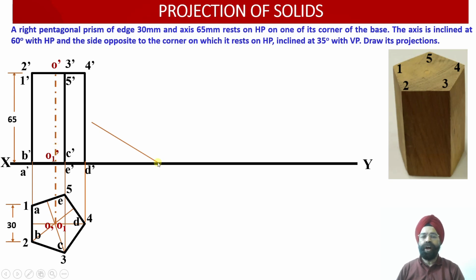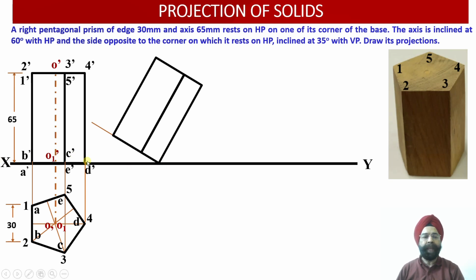So once we draw the angle of inclination of the base as 30 degree, now point D dash will be shifted over here as point D1 dash. Now this is our point D1 dash. The moment we obtain point D1 dash, now you see, using rectilinear distances principle, we are going to transfer these front view elevation projections into the new inclined orientation over here.